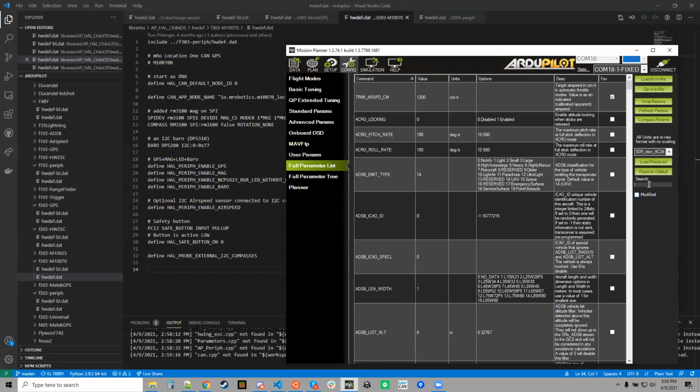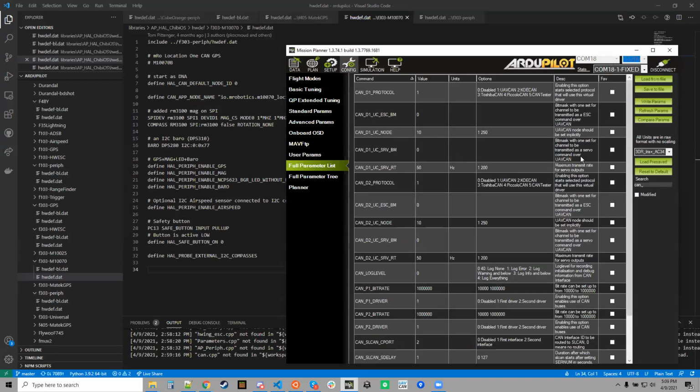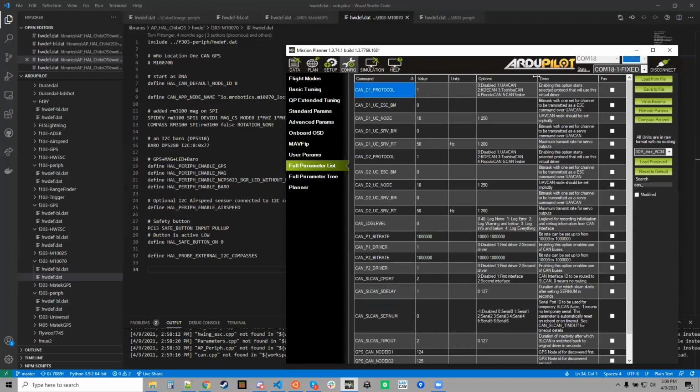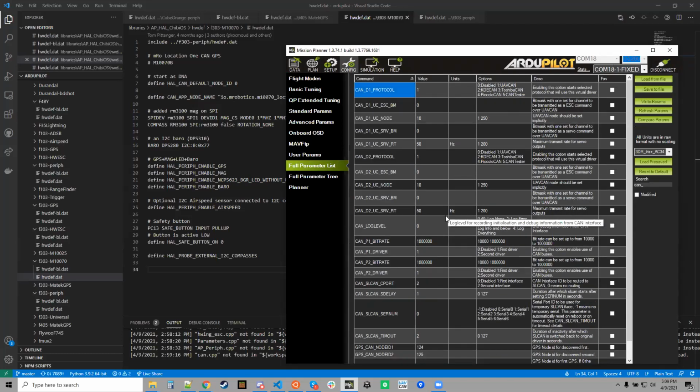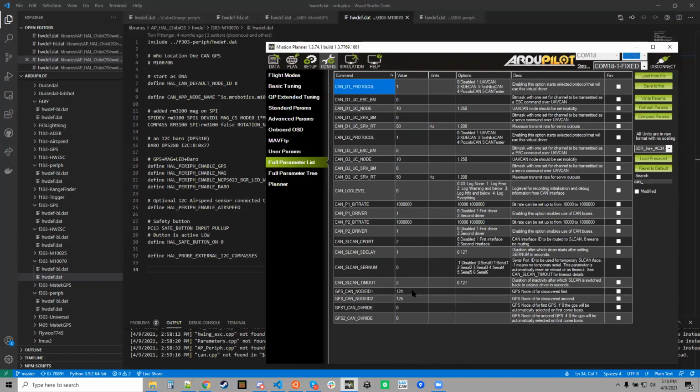And you've got to actively make that decision as a vendor as to whether you want to grab one of the 127 possible node IDs as a fixed ID, or whether you want to be able to just do it dynamically. In most cases, you want dynamic, but there are some cases like the Maytech one where the right choice is to make it a fixed ID because that makes it easier for the majority of your users.